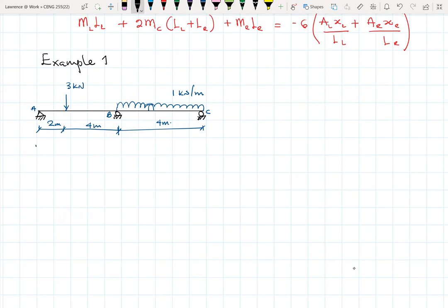Here we are to draw the bending moment diagram and shear force diagram. So I have to draw these two diagrams. Again, this is a continuous beam. The number of unknowns is more than the 3 equilibrium equations that we need. This means that we cannot solve them using our basic structures knowledge from first semester. So what do we do? Here EI is constant.